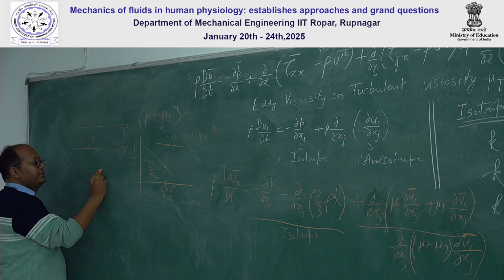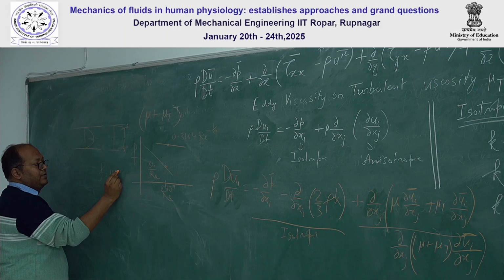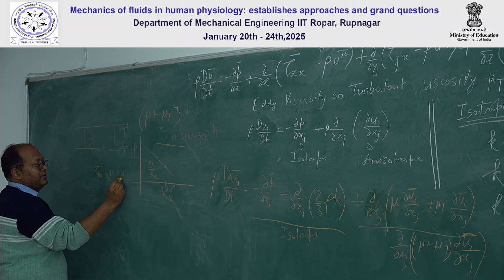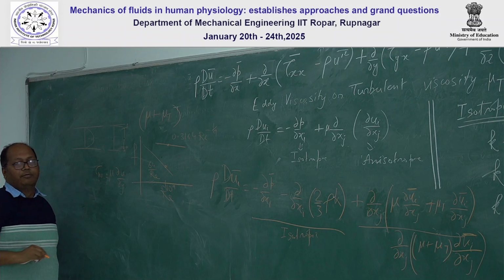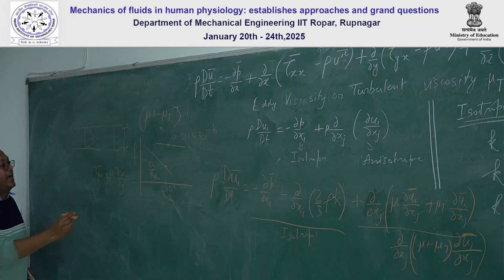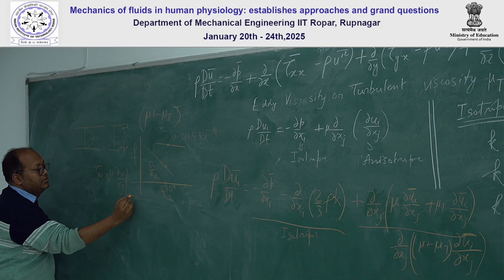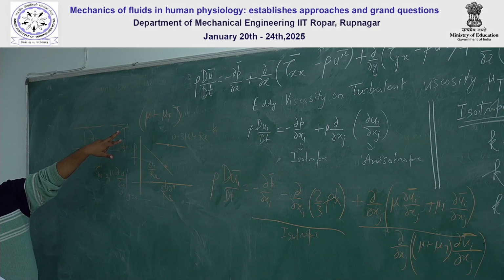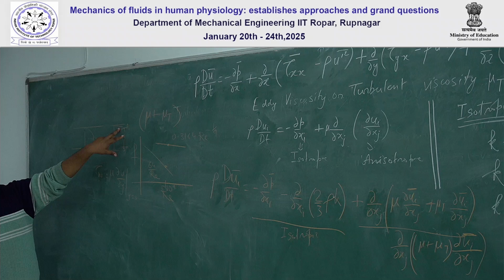Normally for the friction factor we just look at the wall shear, let's say what we write as du/dy, right? So here, at y equal to 0, you can see it is a much smoother gradient, compared to the turbulent conditions, where the velocity gradient is much steeper.